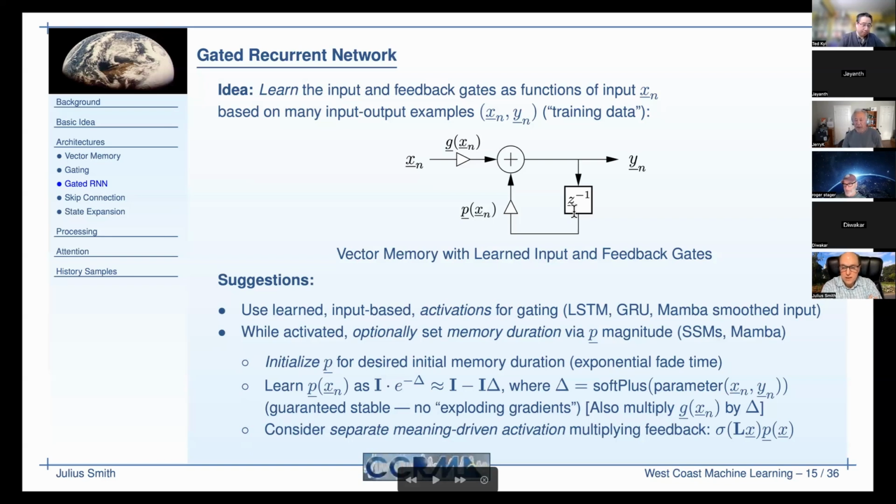Whenever things like that happen and you get good properties, look at the matched Z transformation for filter design, the impulse invariant method. Look at all the different methods for going from an analog filter to a digital filter, and you'll see things like that going on. You normally do that to achieve various objectives like better numerical performance, or maybe you're trying to warp the frequency axis that way. But that's frequency transformations for some purpose, and so you have to inverse Z transform to see what that did to you in the time domain.